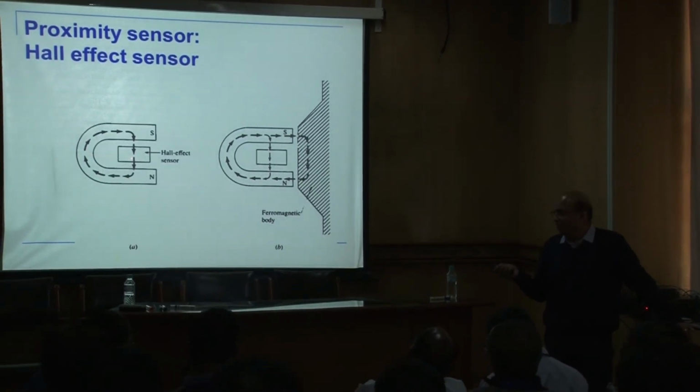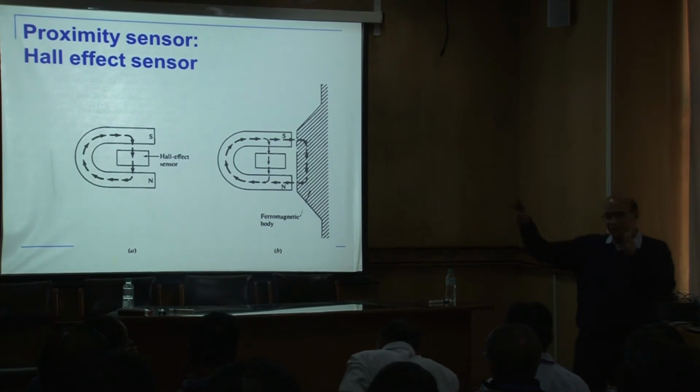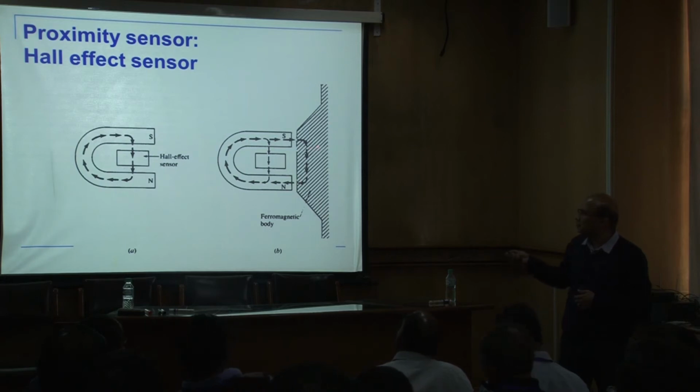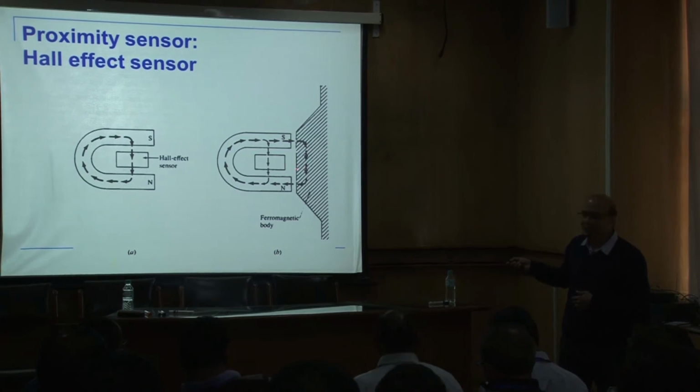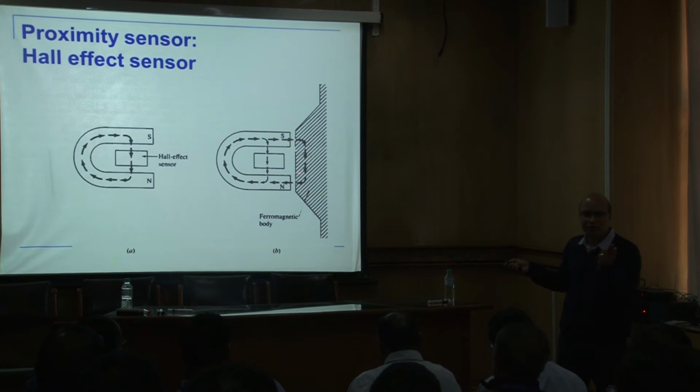So one is at the output of the engine, and the other one is after the gearbox. If you think about this as gear teeth, then when the gear is rotating, this is measuring how many on-offs are coming. Although it's measuring on-offs, 1010, it's the same thing, and it knows how much time, so it knows the velocity now.